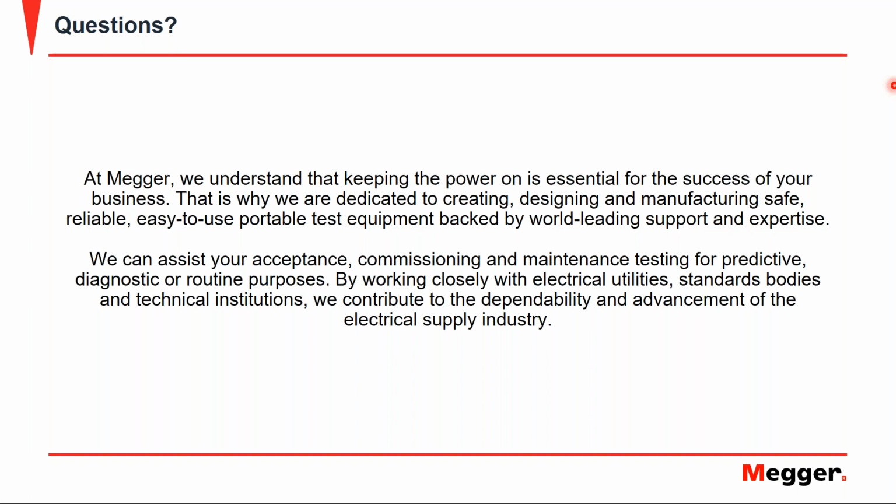So whenever we're doing this type of testing, we have to ensure that both ends of the cable are properly isolated. That means both from any other source of ground that may impede the partial discharge measurements, but also from being accessible by other individuals or workers that might be in the area.